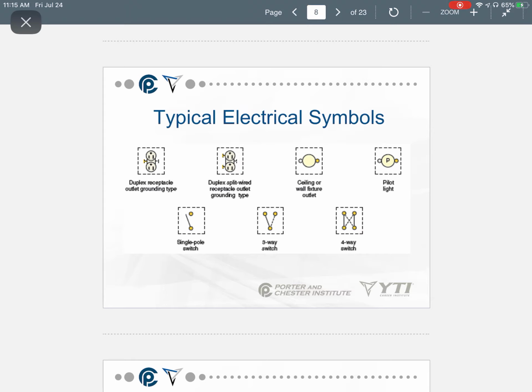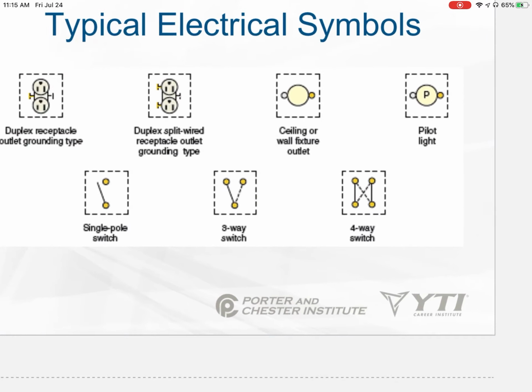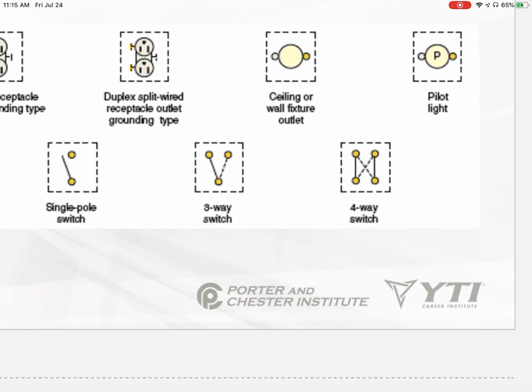Or the other thing is you could add a grounding means, which is probably the most difficult thing to do. So you're probably better off just labeling it as no equipment ground, basically is what it says. No equipment ground, or put in the old replacement non-grounding type plugs. So that's perfectly acceptable because it's grandfathered in.